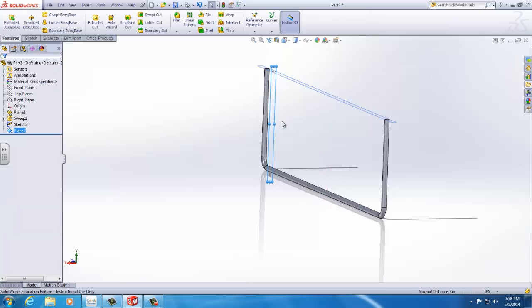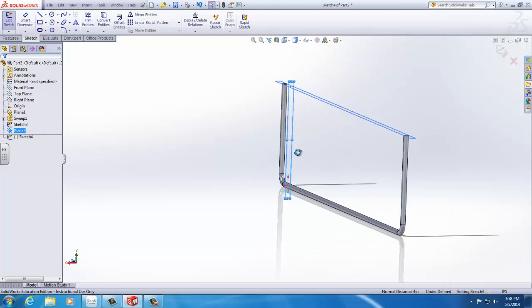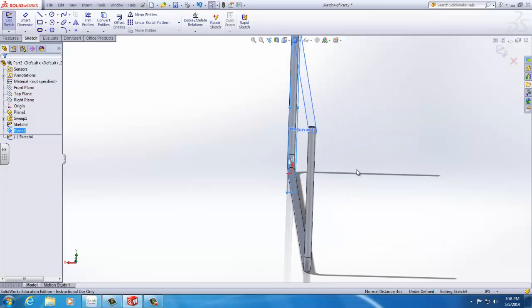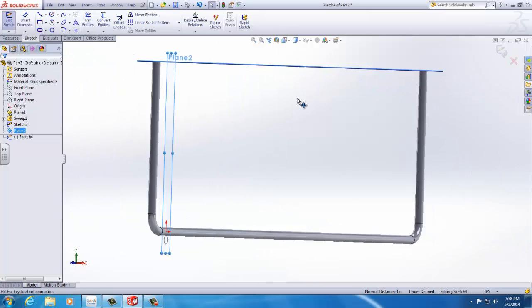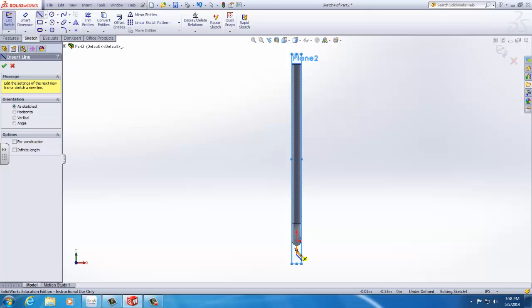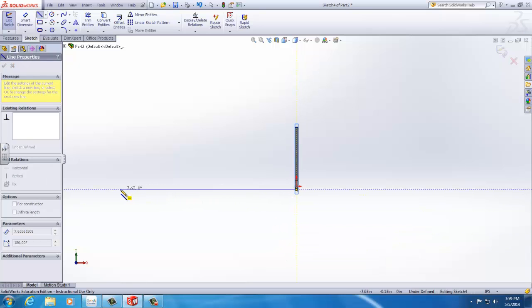Now we need to create a sketch on this plane, so that the top of the canoe matches where the section cut is drawn. So I want to make this match to here. So in this plane, I'm going to start by moving it to that spot right there. So we're going to start from the origin, the center of that circle, and go across. It's a little short, which we can adjust. Stretch it out.